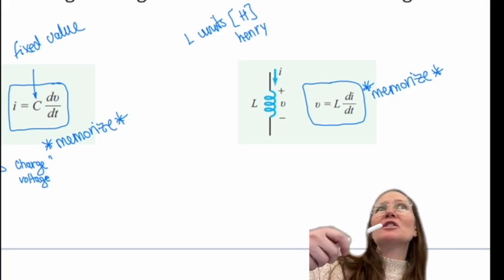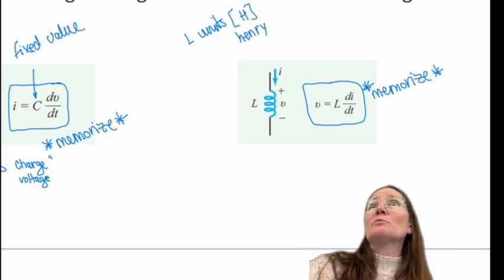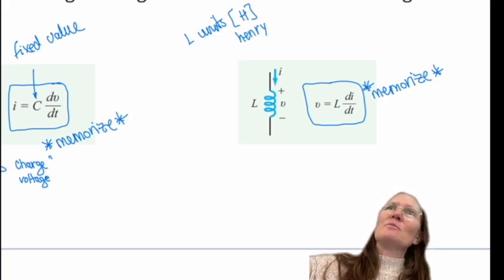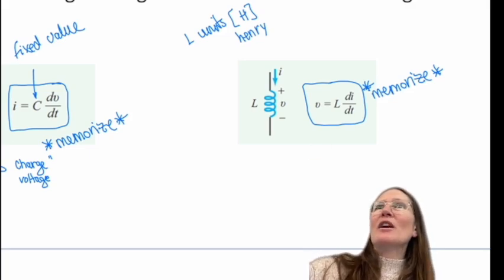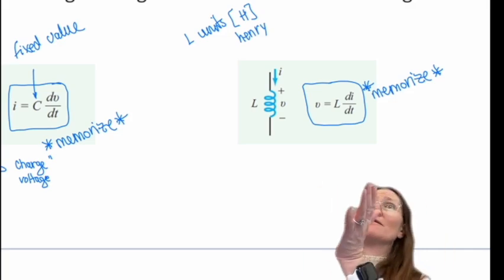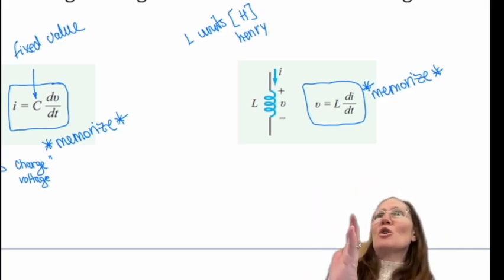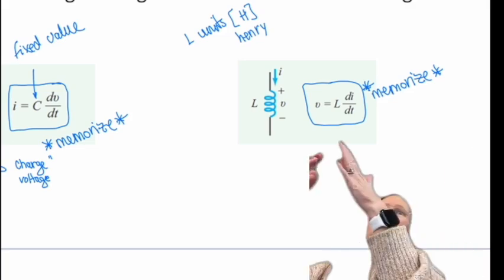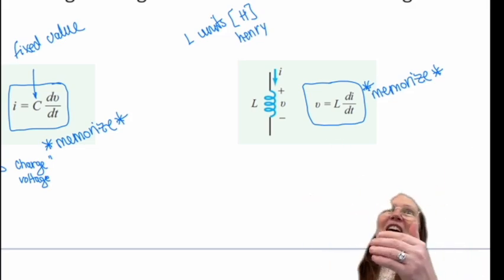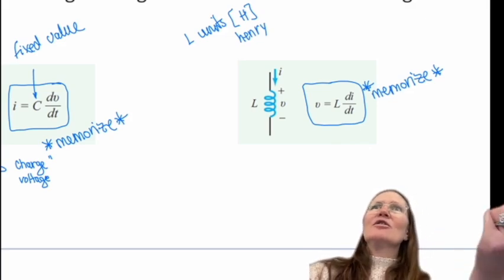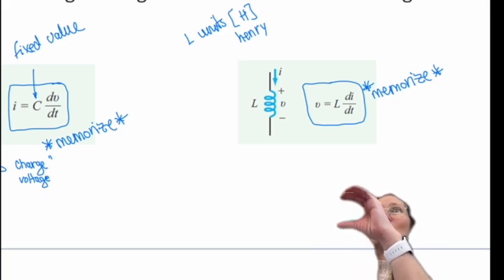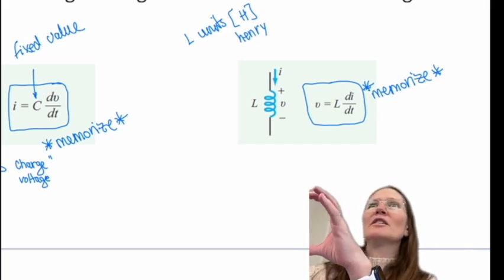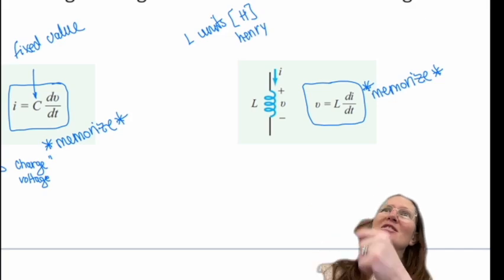And so unfortunately, ideally, yes, a capacitor could be a battery, but because we live in a real world, there's going to be some little bit of connections to something else, or there'll be what's called a parasitic effect, where it will couple with something that you don't want it to and create a dissipation of something. So over time it will actually discharge if it doesn't constantly have that connection. So you can't use it as a battery solely. You can charge it up and then use that until that voltage is gone, but it will actually dissipate over